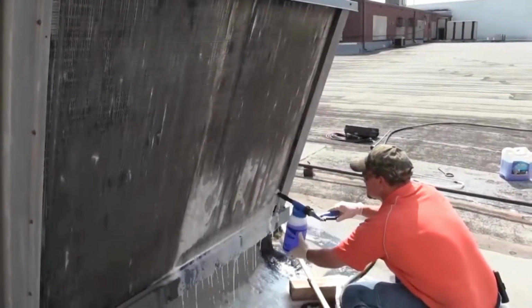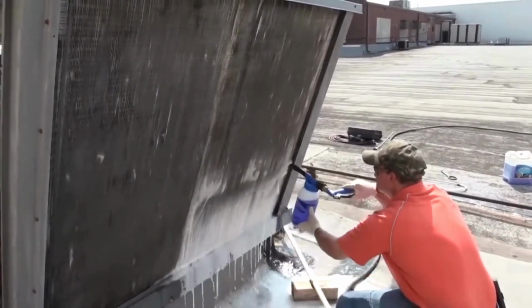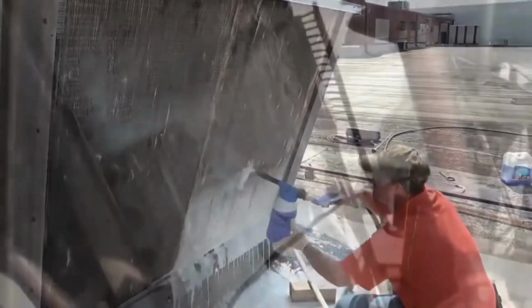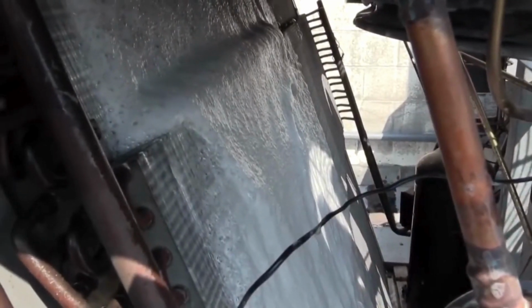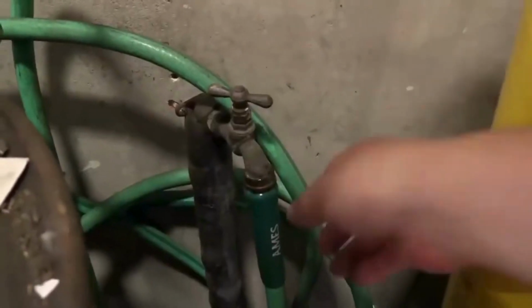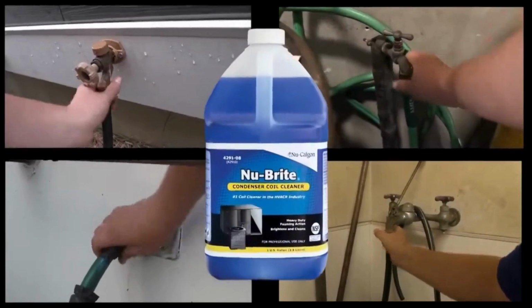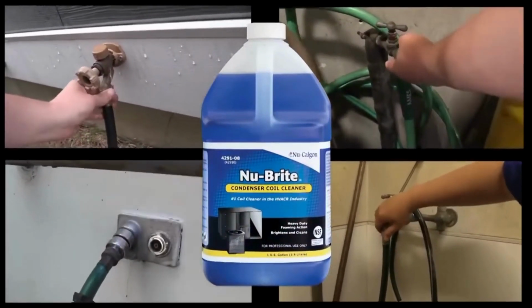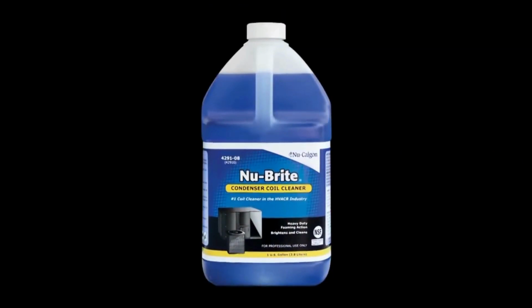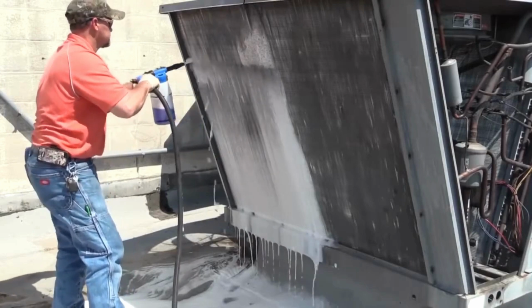Once preparation is complete, use the coil gun to spray the entire coil surface to dispense New Bright or other New Calgon cleaners. Notice how New Bright's foam is produced at a high rate, lifting and holding debris as it expands. All New Calgon coil cleaners are resistant to variations in water quality. That means cleaning coils in a location that has hard water will never affect the performance you expect from New Calgon products. Consistency that is unmatched in the industry. Continue cleaning the coil until the entire surface is treated.